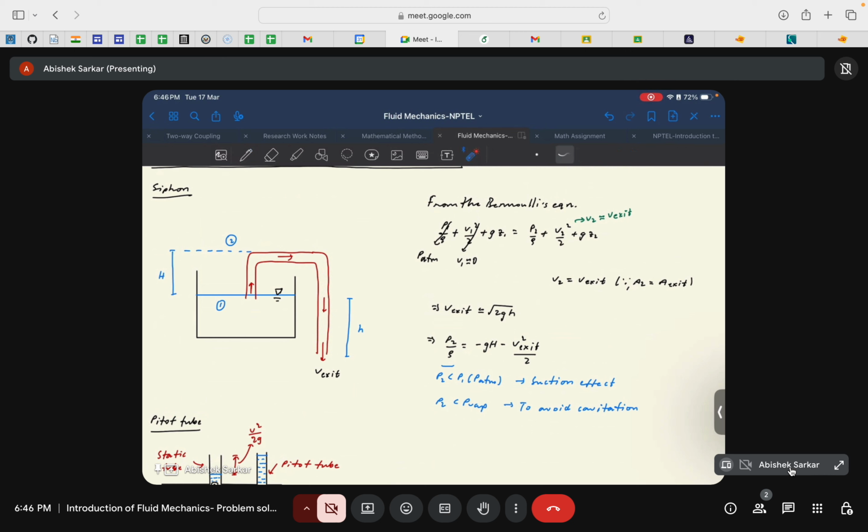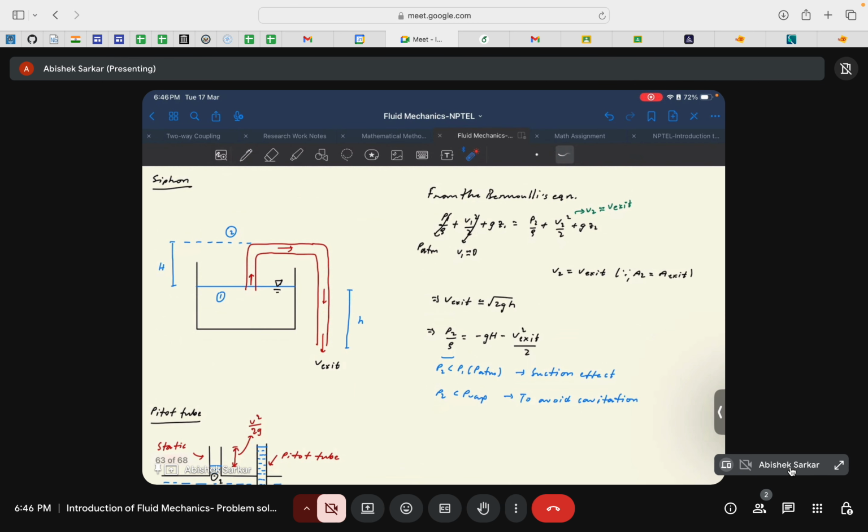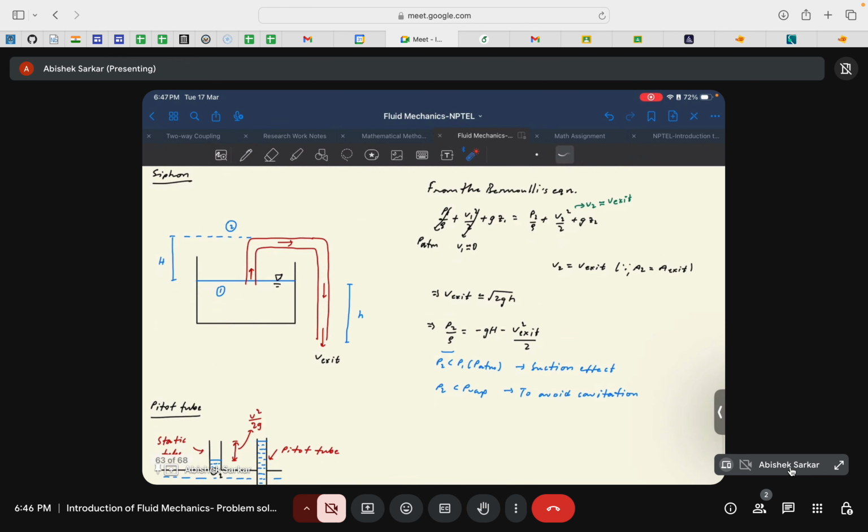Like in this figure itself you can see, they will insert one of the ends of the pipe in the fuel tank, and at this exit they will create a suction pressure, for example by sucking in the fuel for a while. Once they create a suction pressure, the fuel will start to come out of the pipe's opening. It's important to keep the opening of this other end of the pipe lower than the level of fluid inside the tank.